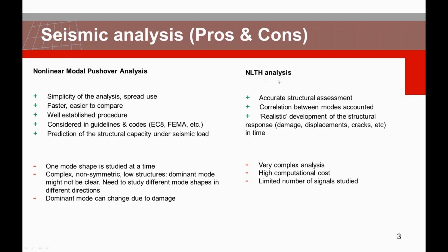On the other hand, the full nonlinear time history analysis provides an accurate structural assessment and also accounts for the correlation between modes. It is indeed a realistic prediction of the development of the structural response, so the development of damage, displacements, and cracks with time. However, it is a very complex analysis at a high computational cost, so we can only study a limited number of signals for the probabilistic analysis.